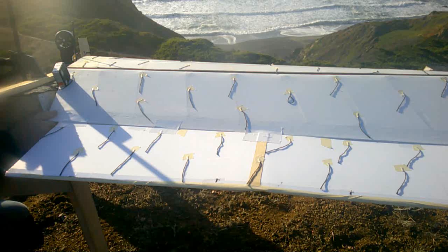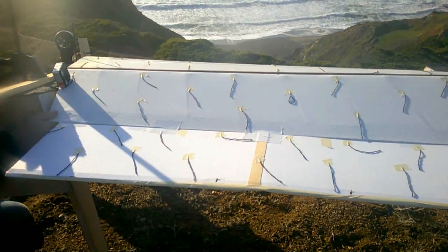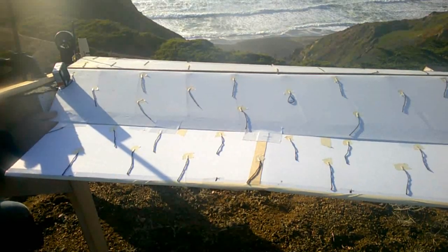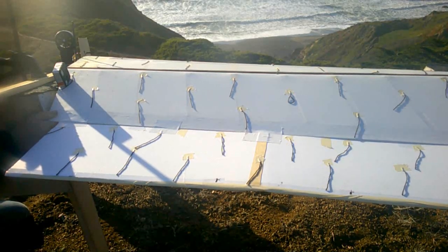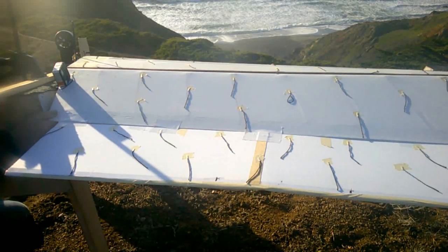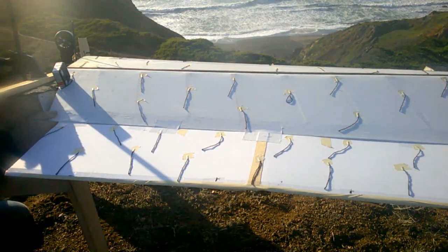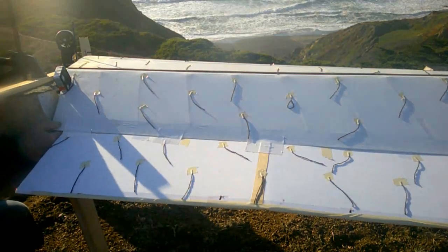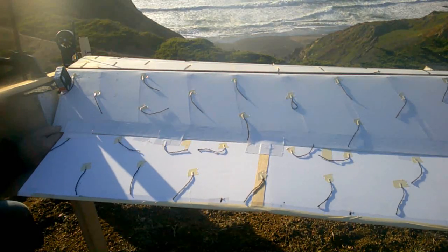And I think here shortly I take it to 20. This was either 20 or, and then I go to 25. But here we have quite a bit of downward deflection on the elevon, and we still have nice attached flow. Everything's well behaved, other than the wind whipping back and forth. It was a gusty day. It's a pretty wind tunnel, but it's not consistently smooth. And in a moment here, you'll see me push it down until there's separation. That's down around 25 degrees right there, and we begin to see the separation.